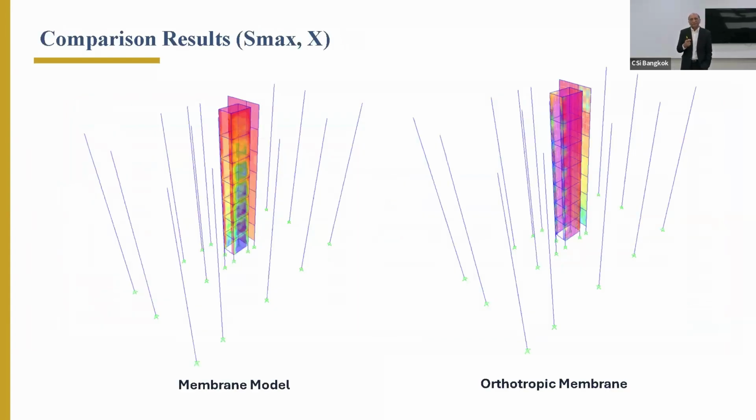And what we can get more from the finite element analysis is the local stress distribution, and you can see here that not all the panels along the height have the same stresses. Obviously, the panels at the lower floors will have larger stresses because of the accumulated forces, and the panels going up will have smaller stresses. That kind of variation of the stresses we can capture from this model more easily.